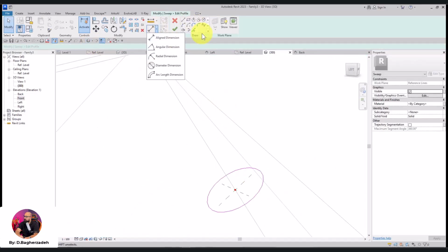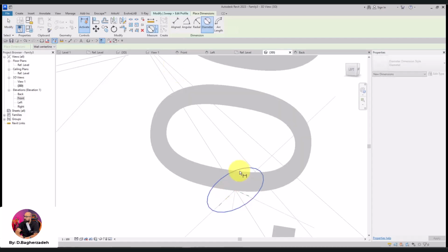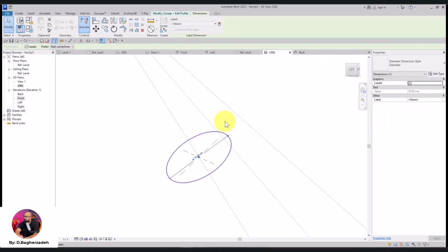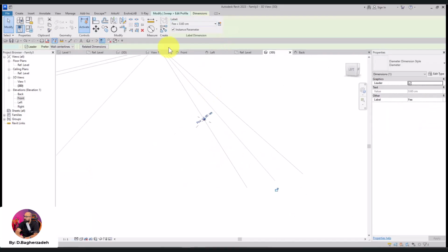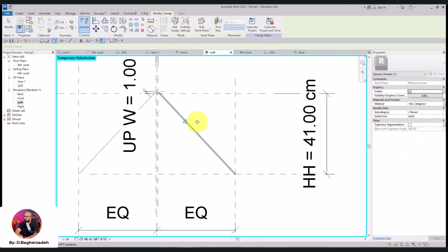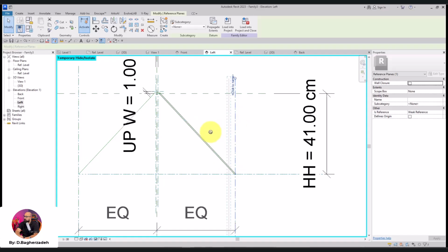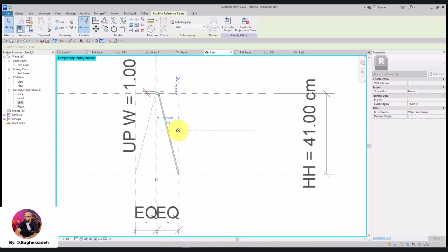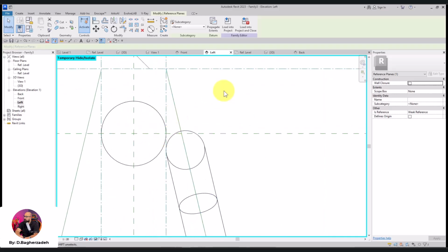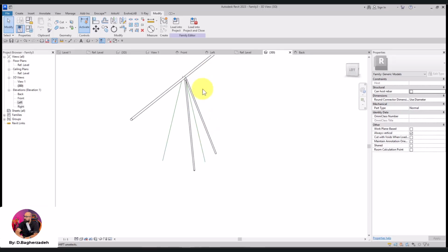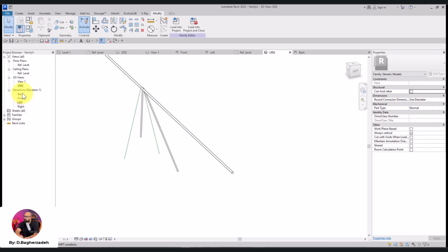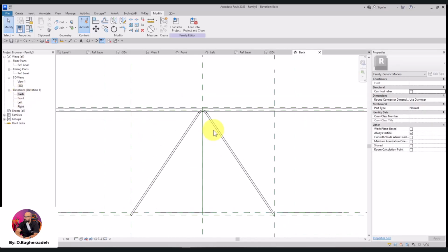Let me see. Align diameter 1 to 1, associating the value of bars diameter, and okay. So this is the opening that if I close it, check it out, and they are placed on the path or on the other pipe, as you can see. And also we have added the fillets to create the bends.